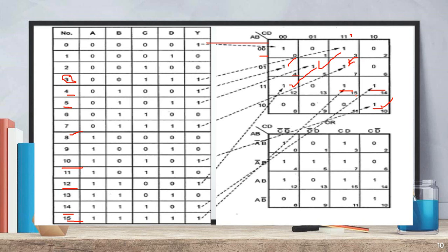In a simple way, we can say that the KMAP is plotted from truth tables with 2, 3 and 4 variables. For the variable combinations having output 1, the corresponding cells are marked with 1s. The other cells are marked with zeros. This is how we can draw the KMAP representation.